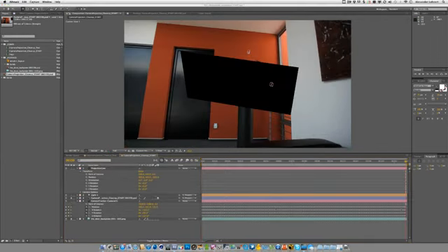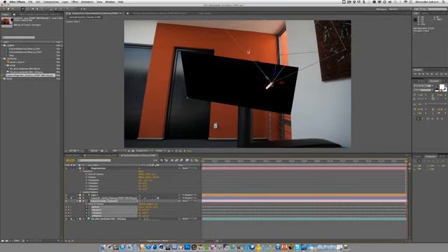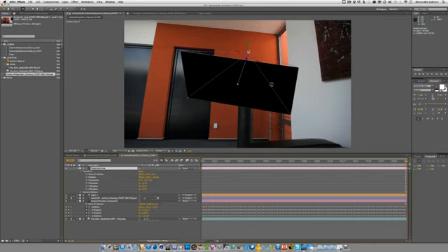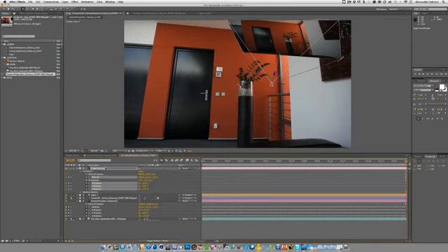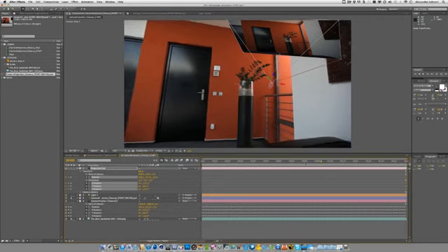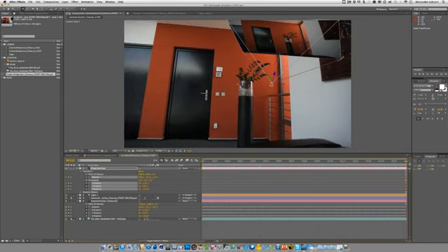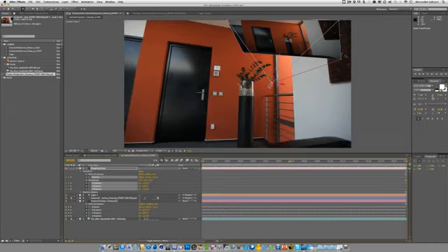Now we're bringing our track camera back into the game. As you remember, we patched the last frame, so I'm just going to get my position values and rotation values from the first frame and copy that back onto our projection camera. And now you can see our scene camera is moving and it's meeting the exact same spot as our projecting camera right at the last frame.